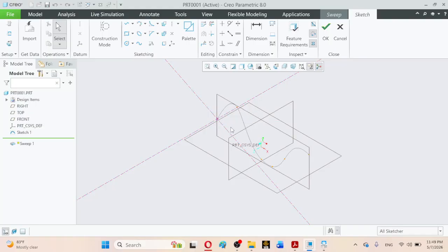Actually these are the perpendicular axes of the normal section plane. This is actually the section plane. The section will be drawn in this plane and will be normal to the start point, so at each and every point. So here for example I am simply clicking on here, though you can set it into the sketch